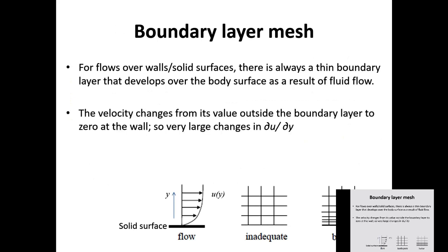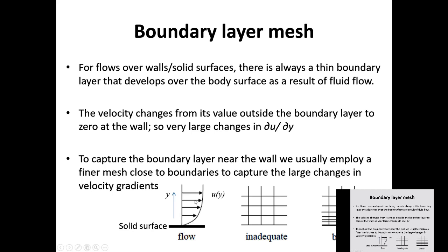So for example, for a boundary layer, now that is your velocity boundary layer. To resolve the velocity, you can see that your velocity changes fairly rapidly in here. So you need to catch that rapid change using a boundary layer mesh. Now this mesh will not catch that.